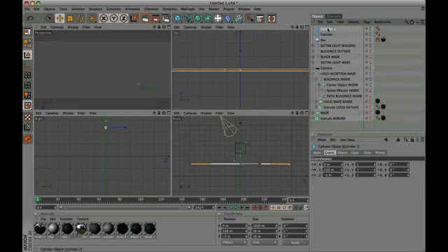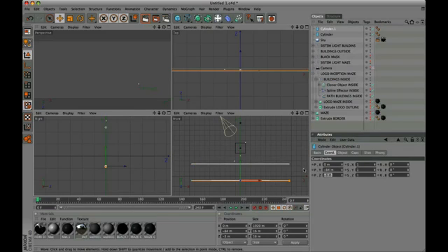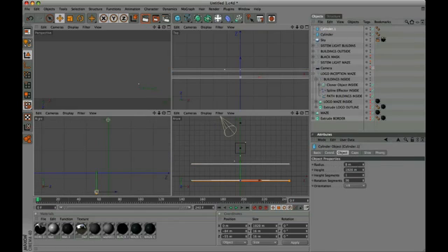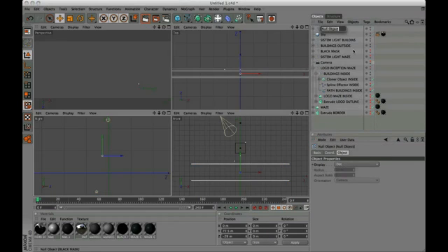Duplicate the cylinder, and modify y, minus 84, and z, minus 55 meters. We modify the radius to 6 meters. We group the 2 cylinders, and rename them building light reflection.